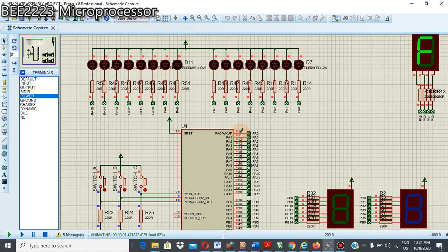Here this LED will turn on when the logic is 0. Why? Because current flows from here, connected to 5 volts, and then it returns to 0 when the logic value here is 0. When red, the LED will not turn on because the voltage is balanced between this part and this part.